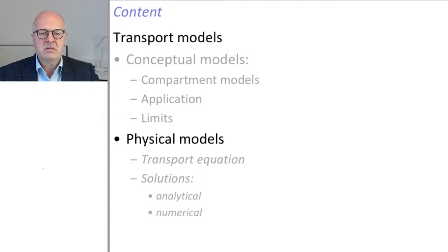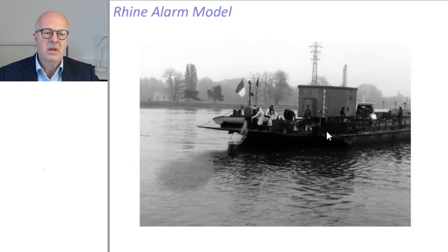And this mixing is described by a differential equation, the transport equation, and this equation can be solved analytically and numerically. I want to start with an example of the application of an analytical solution of the transport equation. These transport equations are called advection-dispersion equations. They comprise the advection and the dispersion.